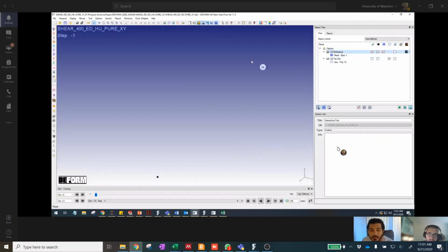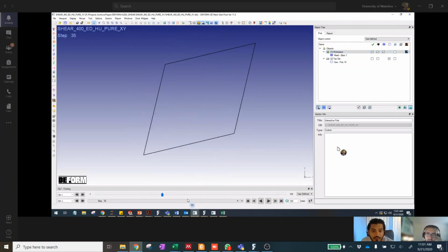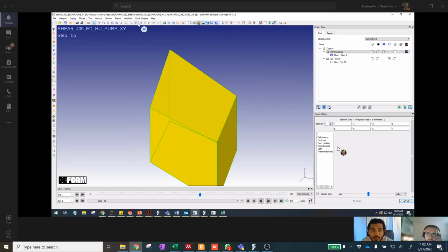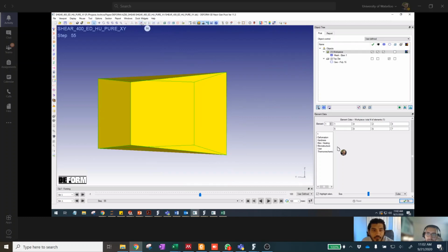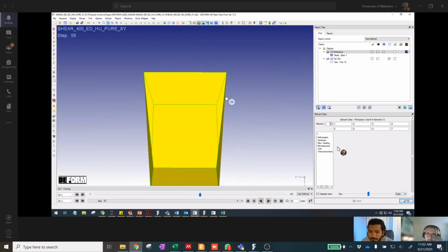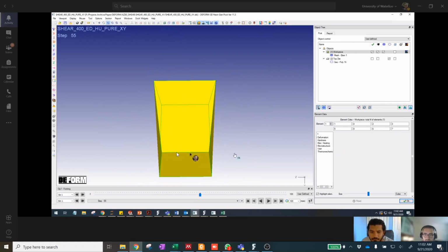I think the boundary conditions that Bezod asked you to do are not correct. In this direction it's correct, but go to the ISO view, then look at a top view maybe. That is incorrect now. That's the reason why you have those stresses collapsing inwards. This side length is expanding, or this one is held rigid, and these ones are allowed to expand.